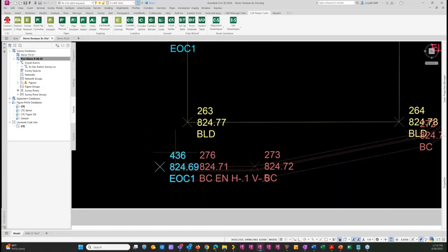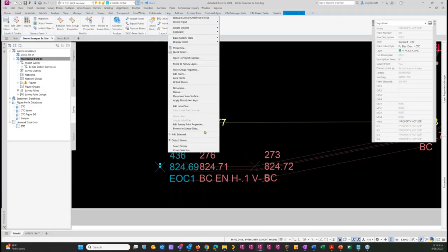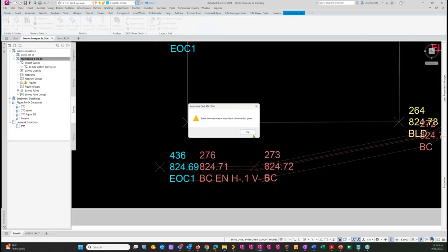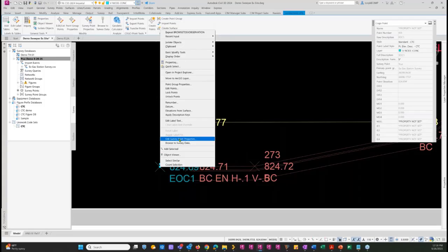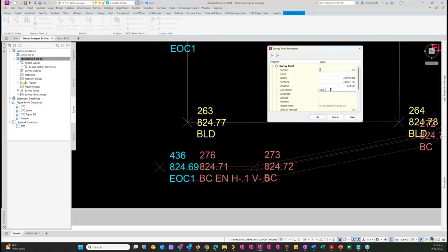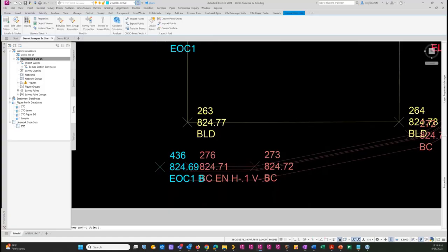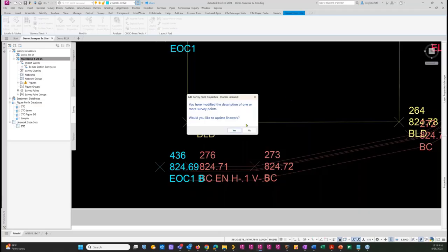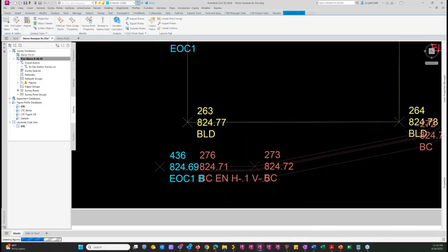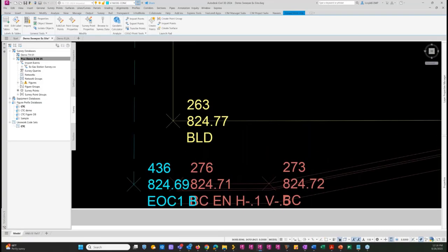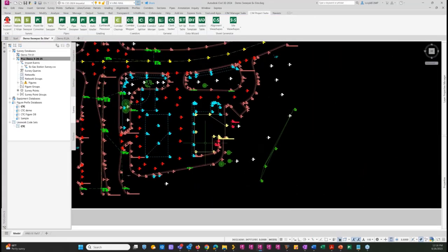So let's add the one more here. We need to add that point or fix that. It looks like it missed. Oops. They missed a line code, a begin code on this one. So I'll just put a B there. Okay. Enter. This time I don't need to bring in my points. That changes automatically, but it brings in the line work. So we've done this a couple of times and now we have the bad lines in here.